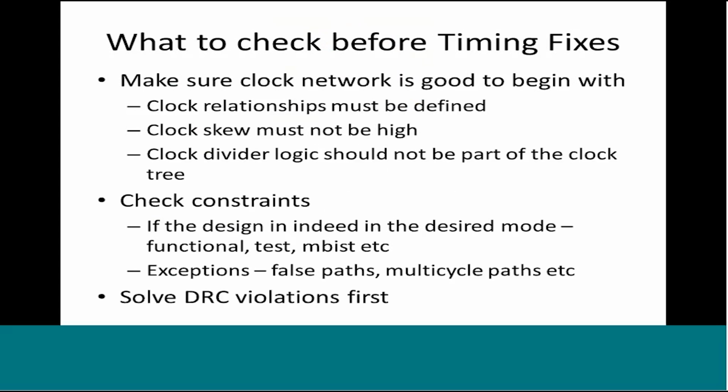I'll first discuss briefly what we need to check before fixing timing. So the regular flow is that once you are done with synthesis, the netlist will go to the post layout stage, to the layout stage where it will go through various steps: placement, clock tree synthesis, routing, and so on. And at the end of all the backend steps, what you will get as an STA engineer. So I am talking from the perspective of an STA engineer, a person who can also work in backend, can also work in the front end design. But I'll focus on the STA part.